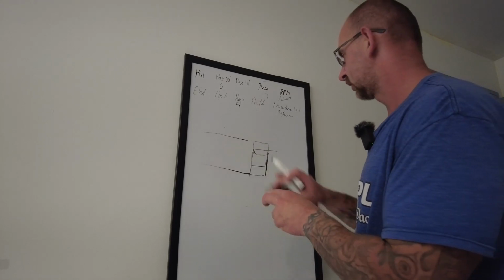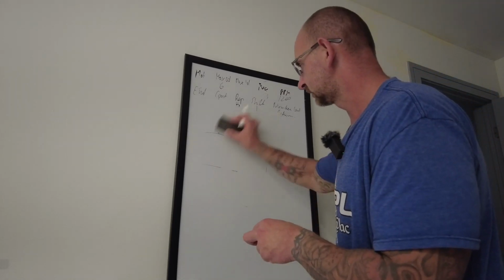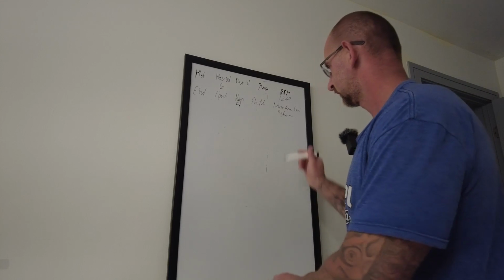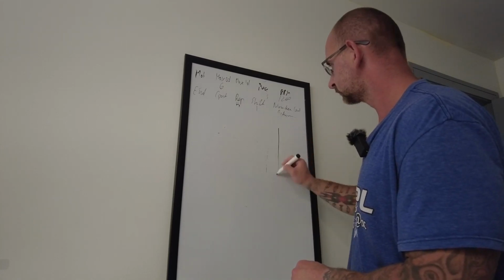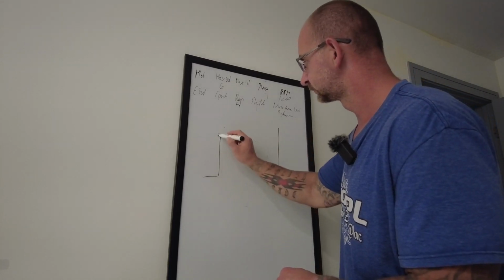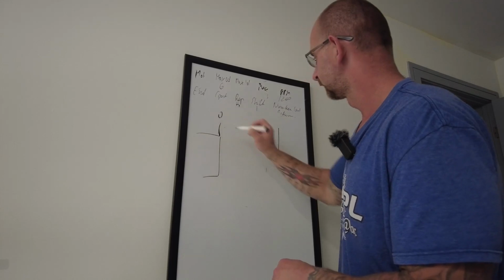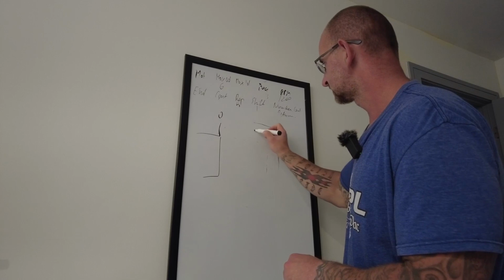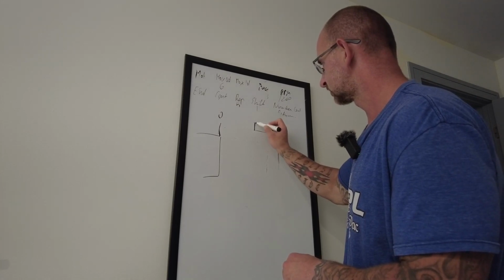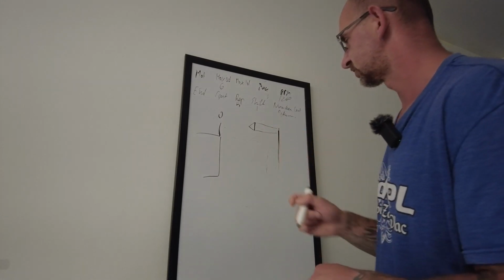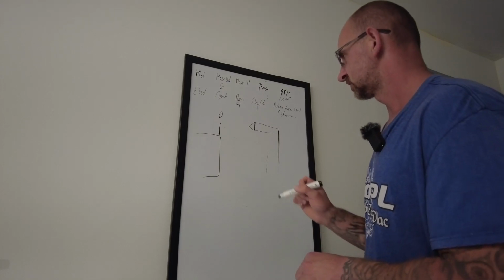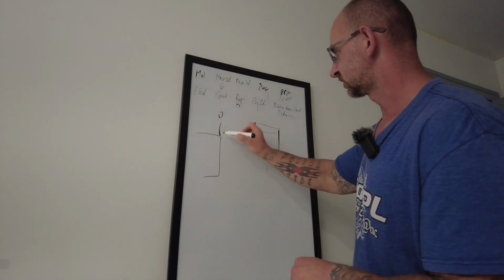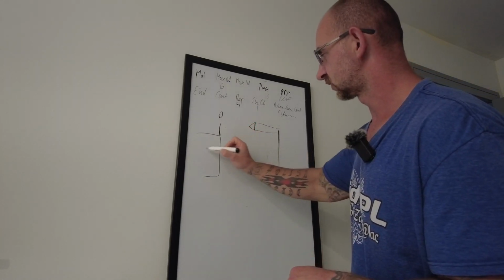For the return, I always go to the longest tool. For example, if this is your turret, this is your part, this is your 0, and this is your longest tool, it's going to be a drill. Well, it's an ugly drill, but it's a drill. So let's say the machine drills over here.